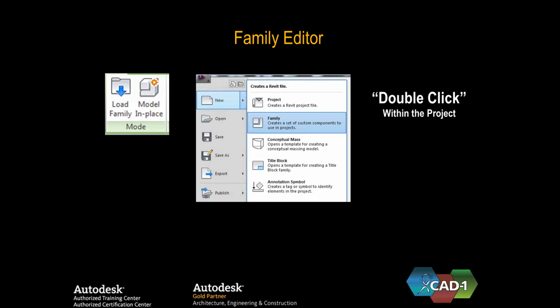The second one is in your application menu. You can go over and just hit the new button there, go over to families and just start a new family. Birds and the bees type of thing. Just get going with the new family thing. And the last one is new to 2013. You can double click on an existing family and that brings you in the family editor.